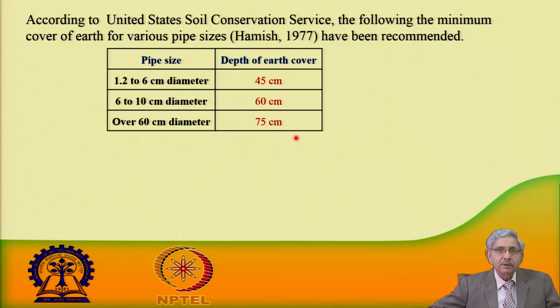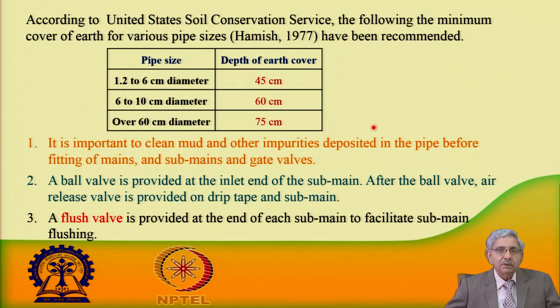It is important to clean mud and other impurities which are deposited in the pipeline before fitting the mains and sub mains as well as gate valves.